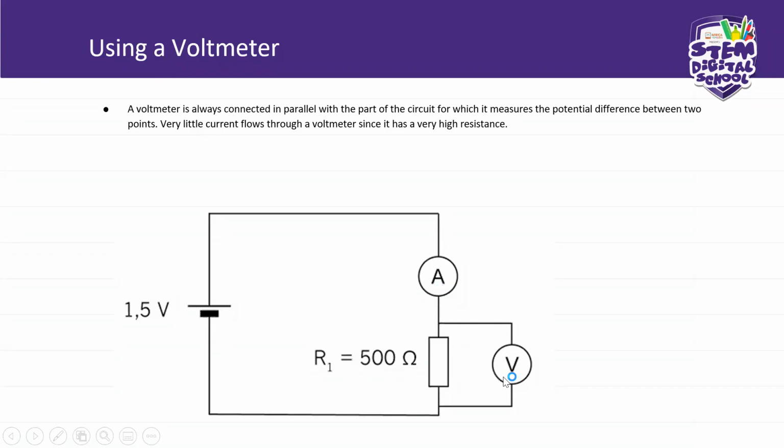But the voltmeter, if we connected it in series, it would give us a false reading because it would offer resistance in the circuit. For now, it is good because the resistance is only offered by this resistor. So we don't need another resistor in form of a voltmeter, but we need a reading to measure the voltage of this circuit.